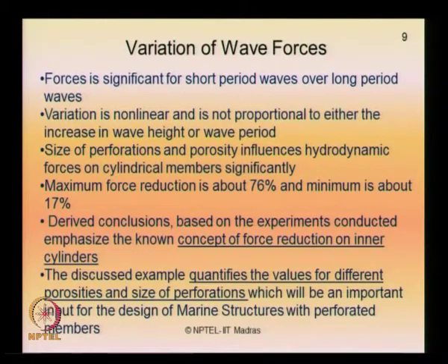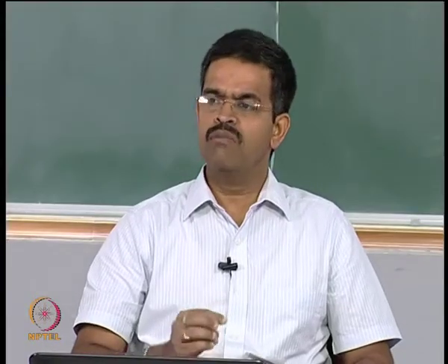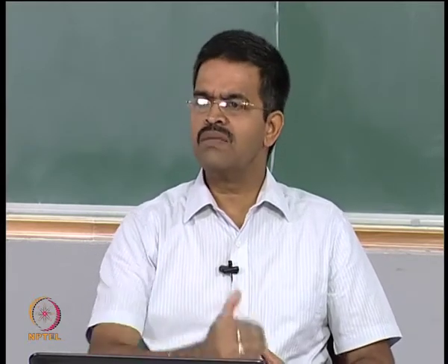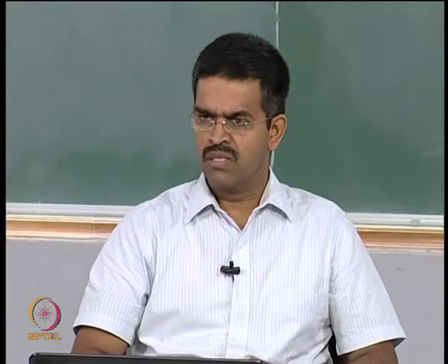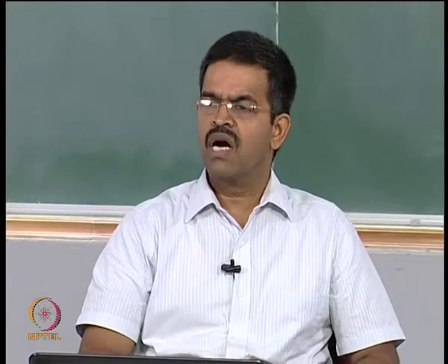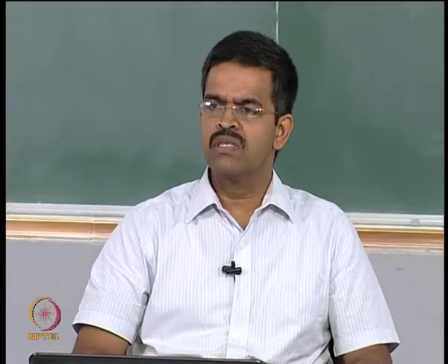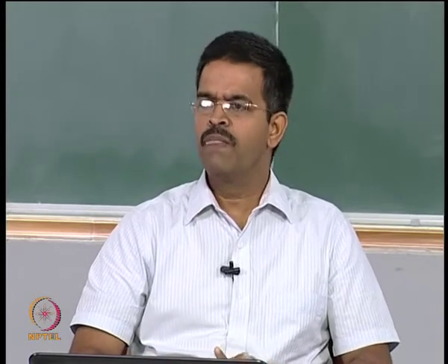One can ask a fundamental question: why should marine structural members have perforated layers? We have seen in the last lecture that perforated covers or porous regions covering solid members reduce secondary responses caused by VIV.